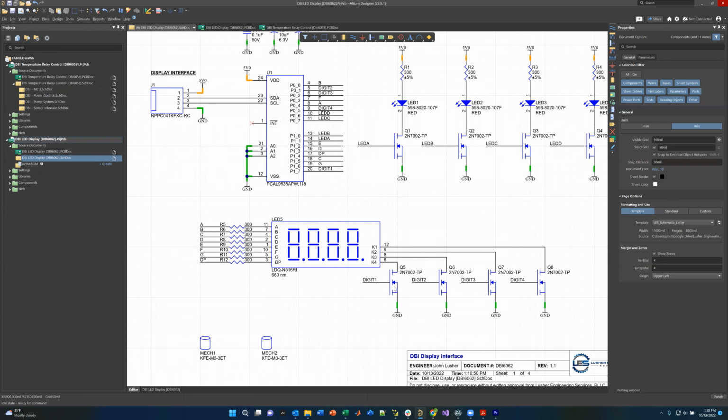You control which digit is on with these cathodes here. These are all LEDs. There are 1, 2, 3, 4, 5, 6, 7, 8 LEDs being driven for each individual digit, and each LED is one part of each segment, and of course the decimal point for each one. When I turn on the cathode, if I wanted to light up all the same value, if I wanted this to say 8888, I would light all the segments.